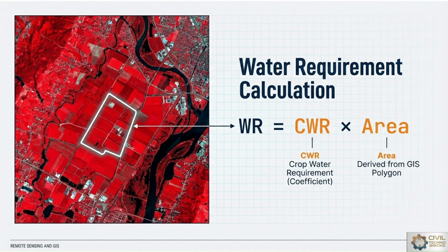So we have to target the area by using GIS, satellite imagery or aerial photogrammetry. We have to multiply the coefficient of crop water requirement, or the water requirement of any crop, with respect to the ideal condition or the climatic condition, so that we can calculate the water requirement. So crop water requirement analysis is the most important point for the primary GIS application in irrigation, where we have to determine the actual water available and actual water requirement.